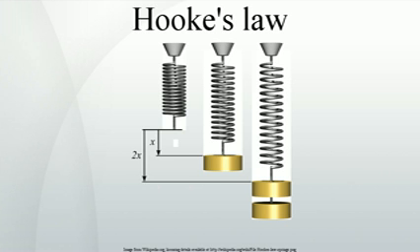Thermodynamic basis. Linear deformations of elastic materials can be approximated as adiabatic. Under these conditions and for quasi-static processes, the first law of thermodynamics for a deformed body can be expressed as, where the first term is the increase in internal energy and the second is the work done by external forces. The work can be split into two terms, where one is the work done by surface forces while the other is the work done by body forces.